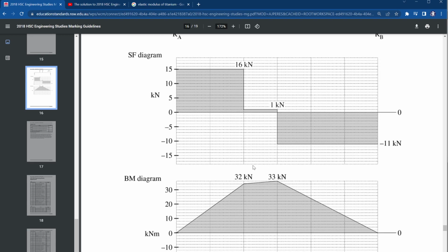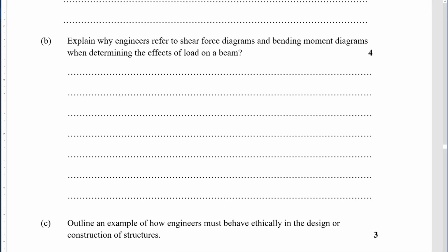Oh, I should notice that this diagram is actually wrong. It says 32, just to show that even the HSE makes mistakes. So 32 kilonewton meters is the unit on this diagram. But yeah, you would design for 16 kilonewton meters for the whole thing, and then you'd add an extra, double the steel for the 32 or 33 kilonewton meters at its highest point.